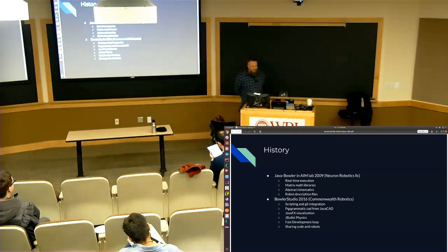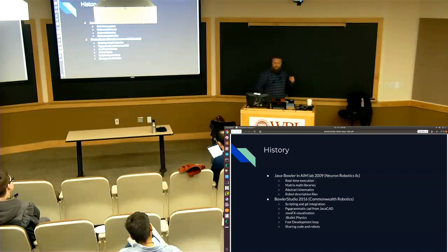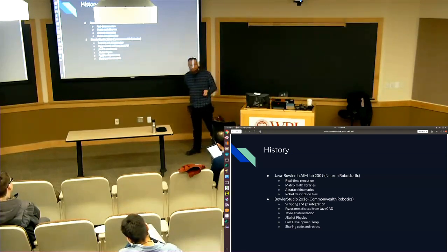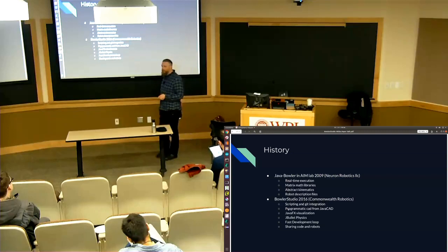So what we defined is a system of abstract kinematics. What are the commands that every kinematic system has to deal with, no matter what? Set in task space, get task space, keeping track of all the fiducials and relative positions of your body. What is generic can be implemented for all of them. What is unique to a particular robot should be only the forward and inverse kinematics. And for systems that are defined as a collection of kinematic chains, the forward kinematics can be solved for you entirely.